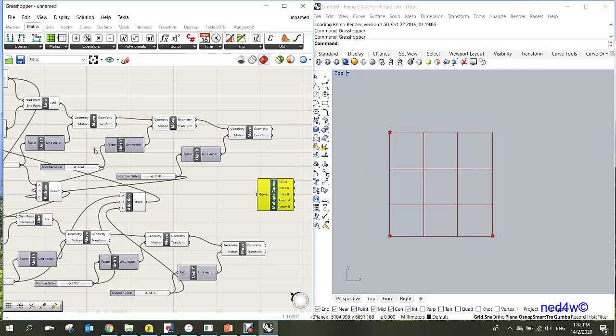Okay, so again, as I mentioned earlier, click this line and then put that one on the curve, and then this geometry line put on the curve. But look what will happen. The first line that I picked vanished because it always uses the last link that you do. But if you just simply press the shift key and then link that one, you will be able to combine all these lines. So I'm just linking all the Y coordinate lines, and then to add the points, we can press the shift key again and link the curve.